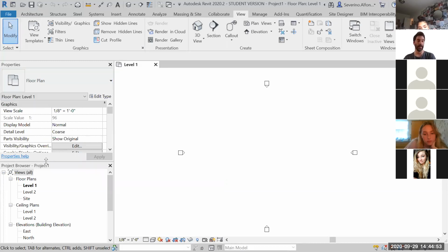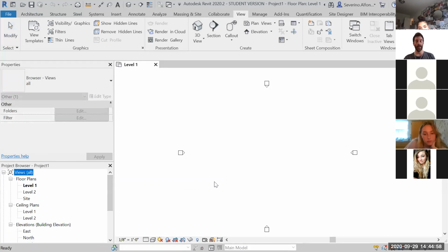Another must and fundamental is the project browser. You can think of it as, like in Rhino, which has 4 different views, such as perspective, top, front and right. Here you can create thousands of views of the same thing. It's just that you're cutting the thing horizontally at this level, horizontally at that level. You're creating this cut, this other cut. So all of the different ways of seeing a project will be manifested here, and you can double click on them and see that particular view of the same project.